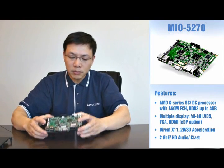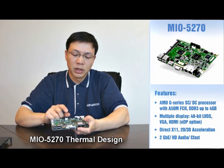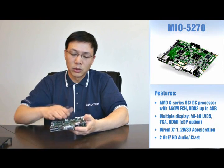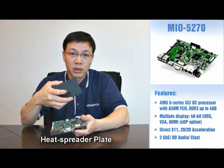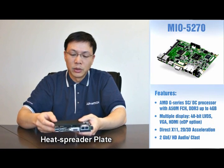In this case, with the MIO-5270, we have two designs to help with that. One, we have the heat generating components like CPU, chipset, and also the DRAM on one side. So other than the traditional heatsink for general purpose, we also have a heat spreader plate that can easily adapt all the heat generating components into one piece, and then we can use the chassis.